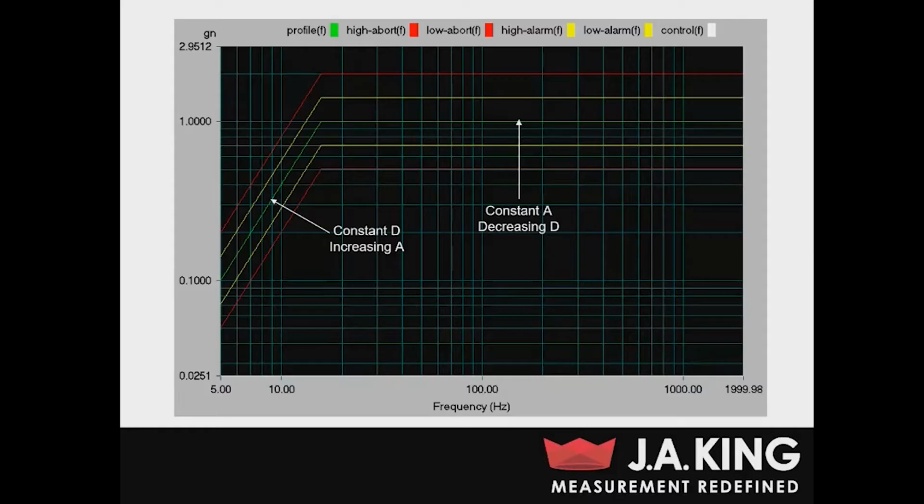I also want to point out the axes on this graph. You can see both the x and y axis are logarithmic. The reason this is so important is because it's going to enlarge small acceleration contributions. This is going to help them actually show up on the graph so you can see them. You can be sure that you don't miss any spikes in acceleration that way.